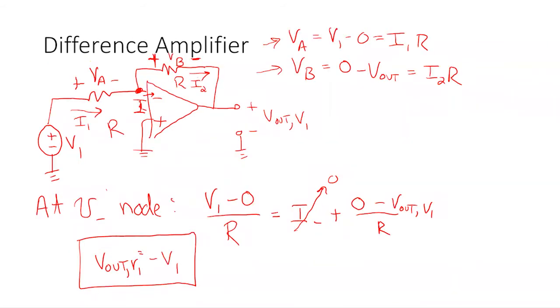Magnitude wise, this is a good time to talk this through. Let's say I had just this circuit right here. What is the gain there from input to output, V1 to output? It's -1. That's not no gain. The term that we typically use is the magnitude of that gain. If I call that gain A, that gain is -1. V out over V in is -1. Magnitude wise, that has what I call unity gain. We are careful to use the term unity gain. That's what I learned.